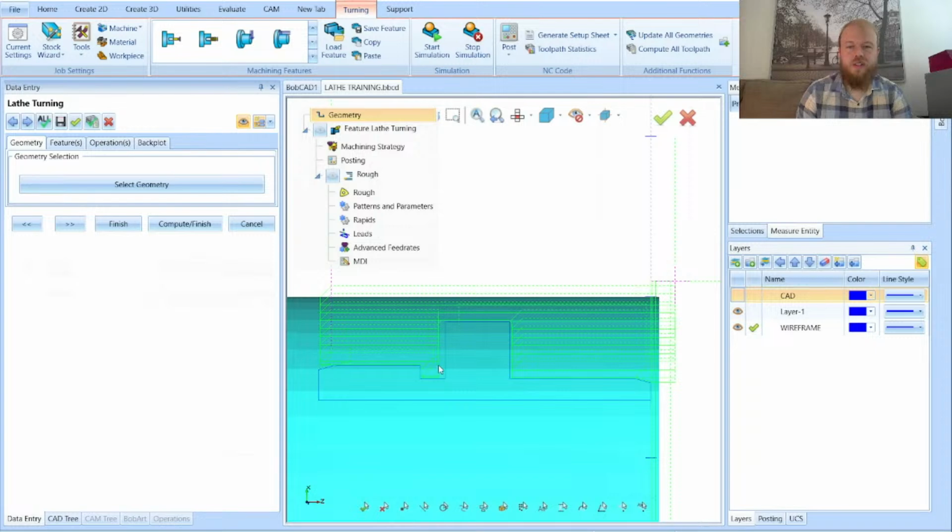All right, I'm looking at the toolpath so far. It looks pretty crazy. It's coming down, going across from my first pass, coming up and out, and back here, coming down to the next pass. The next pass is going to rough all this out. Somehow it's going to try to rough all of this out and try to rough out the groove here. So we don't need all of this toolpath. We'll look at options on how to remove the toolpath for the groove, and also ways to avoid this area because the tool is not going to be able to fit into this area here.